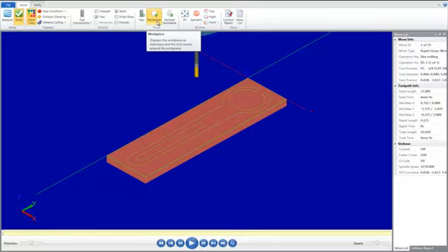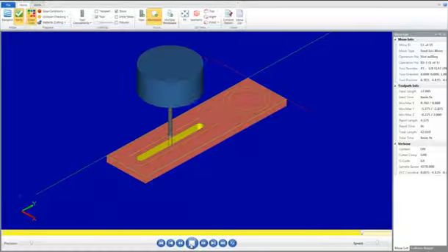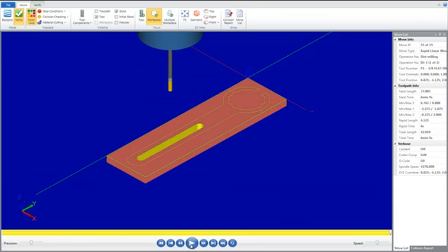As you verify toolpaths, Mastercam displays additional information such as the X, Y, and Z coordinates, the path length, the minimum and maximum coordinates, and the cycle time. It also shows any collisions between the workpiece and the tool. You can now select the Play Simulation button to verify your part. Your part will appear as shown. You can now exit Verify.